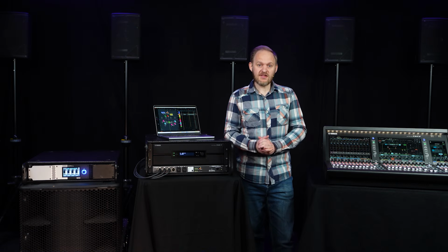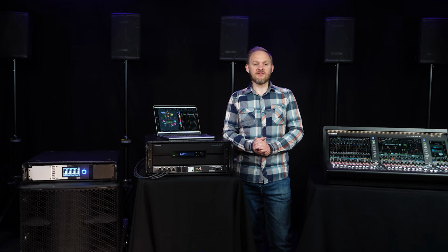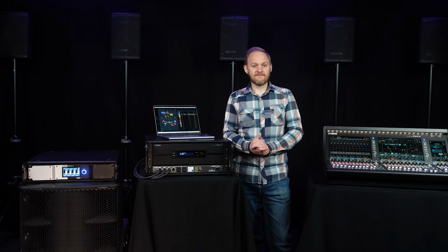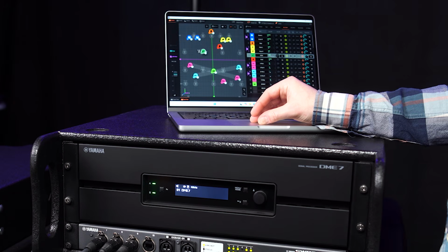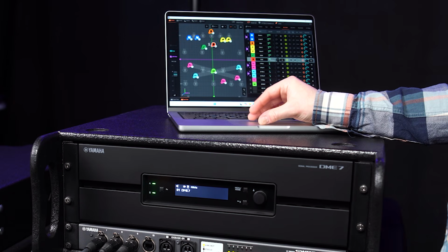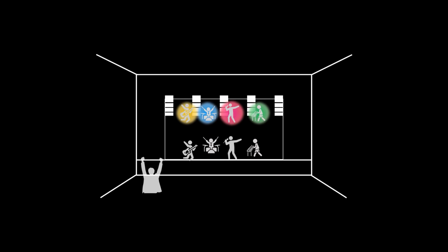Now let's consider a typical and practical immersive audio system for live events. Instead of a conventional stereo main speaker system, we expand it to 5 or 7 speakers, moving from stereo to frontal 5 or 7. We then combine this with object-based mixing by placing audio objects at the positions of the performers. This allows for natural sound image localization, aligning visual and auditory cues and enhancing the sense of immersion.